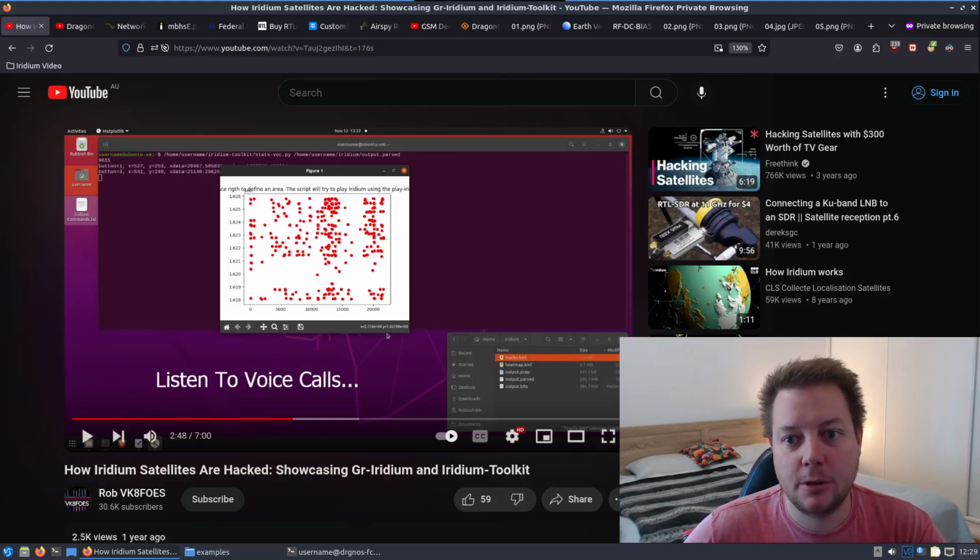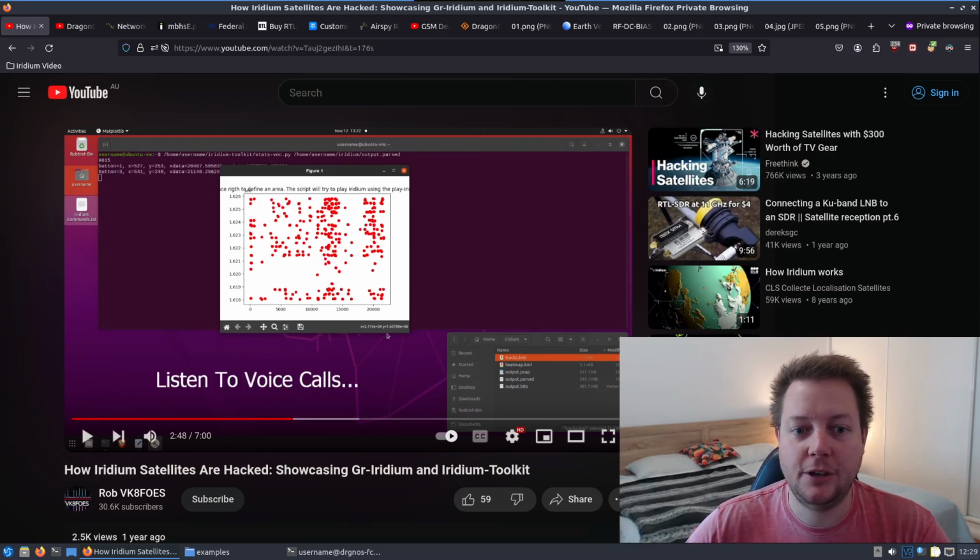It is Sunday the 12th of May 2024 and today we are going to be covering the topic of Iridium satellite decoding. This is a subject that seems to be trending somewhat among my viewers at the current time because I've observed a sharp increase in emails and comments on my videos asking about it. So this video will serve as a comprehensive guide on setting up an Iridium satellite ground station and how to navigate the software decoding tools in Linux.